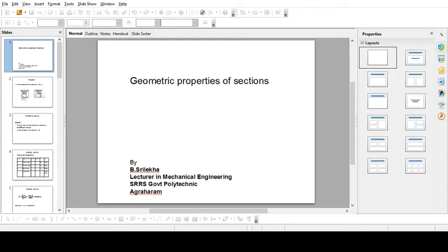So now the position of the centroid. We know that x bar, the centroid about the y-axis, the x coordinate, is a1 x1 plus a2 x2 plus a3 x3 by a1 plus a2 plus a3. Right? So it is 24,097.359 by 1028.25. So it will give you a value of 23.45 mm.